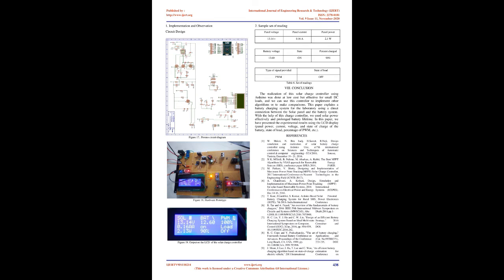In this work some simplifications have been introduced in the implementation of the 4 different charging stages of a lead-acid battery. 6. System description. The solar panel is a device which converts light energy into electricity. The MPPT charge controller is the circuit combining sensors, buck converter, and switches, which is used to maintain the battery at the highest possible state of charge, and when it is fully charged, it detaches the battery.